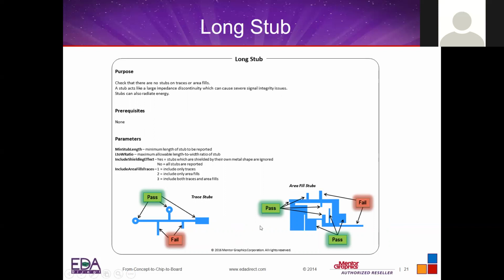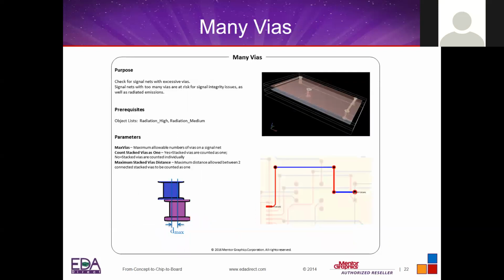And another design I've seen where it's a clock, for example, they have both series and parallel termination, and they pick one or the other. One is to work on the bench and just leave the board as is. Well, guess what? Now those stubs are there, and those cause reflection. They distort the waveform. You don't do that. You don't have the space to do that anymore, and you can't just go out and solder and unsolder components like this.